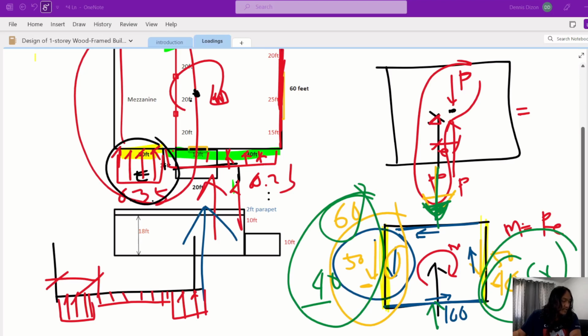And then y, distance y, where is it? Oh, here. In zone with y should be the greater of 6 meters or 2 times z. So whatever is the value of your z, multiply it, and then choose whichever is bigger, 6 meters or 2 times the z value.